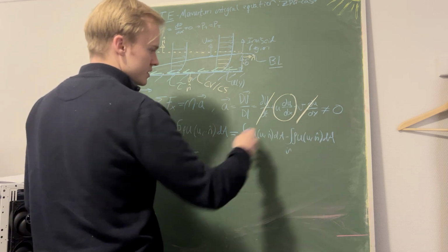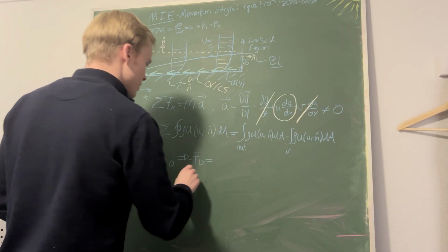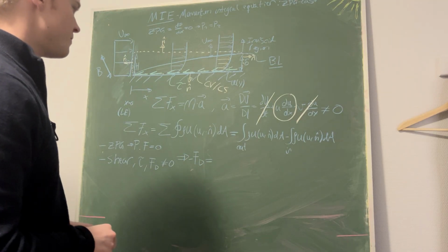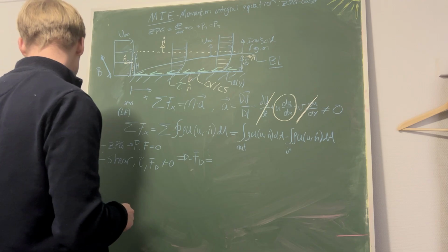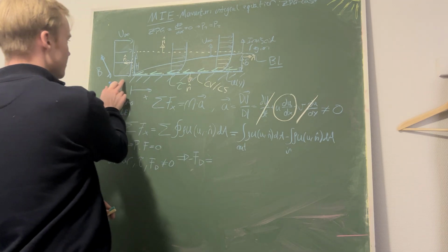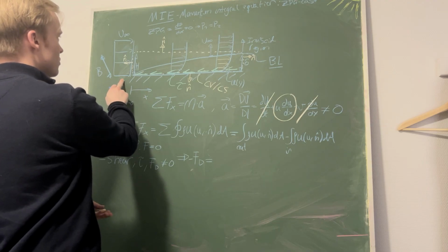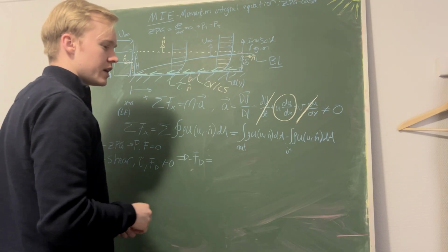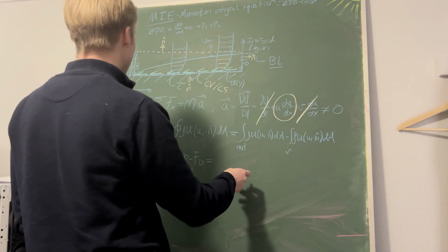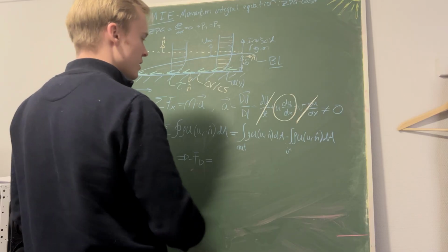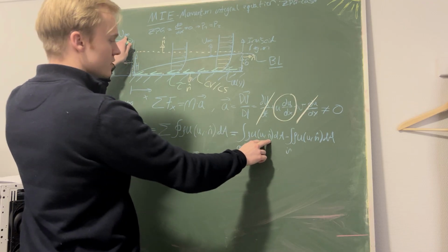Now we compute this net flux integral. So minus Fd, our drag force, should be, if we integrate this, if we take what's coming in first, this is in, right? We have our uniform flow. This u infinity is not a function of any height, it's a constant. So we can basically drop the integral, and we have the dot product of our u infinity with the normal vector.